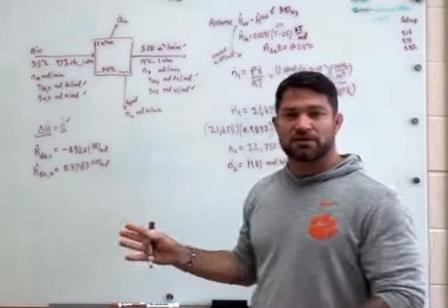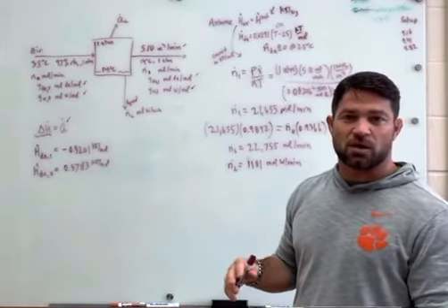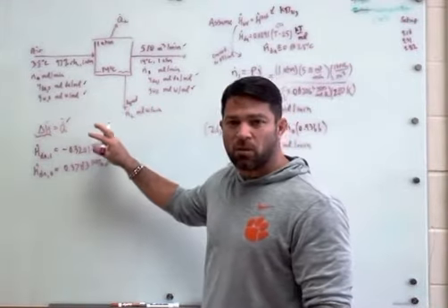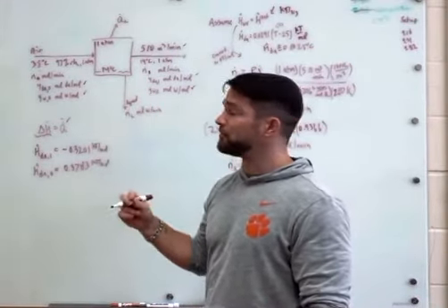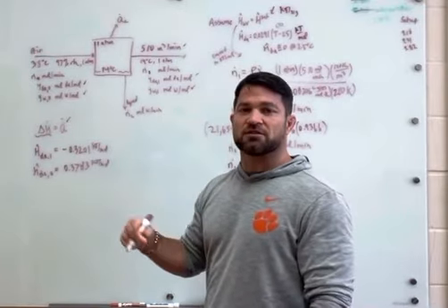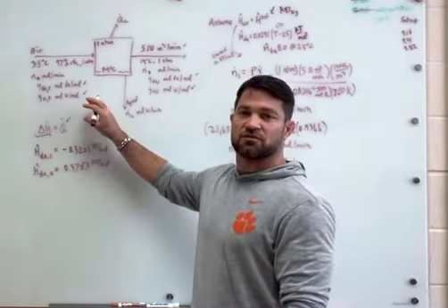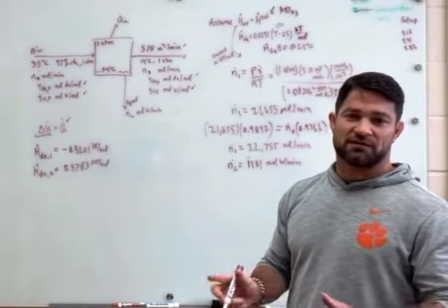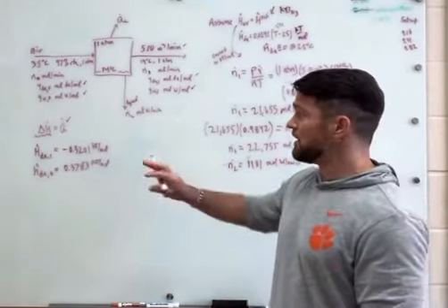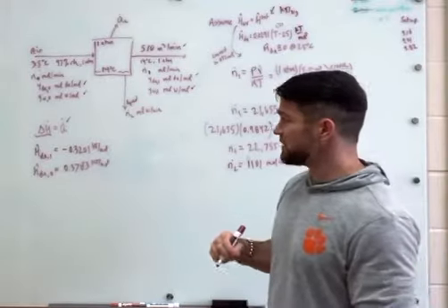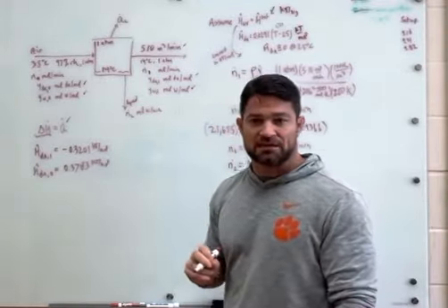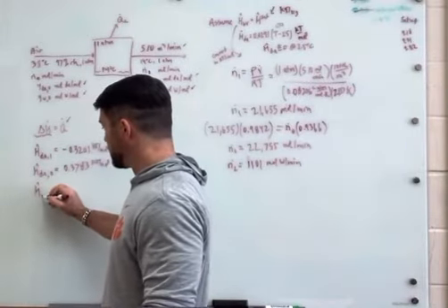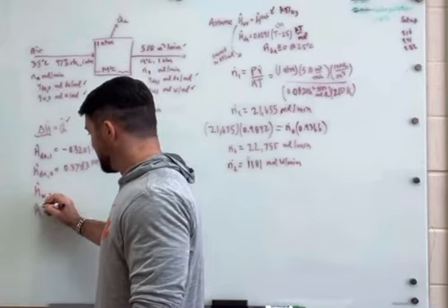And it's okay that we have a different reference state for each one, because we're effectively calculating the change in enthalpy of the water. It's all versus the same reference state, and then also the changes in enthalpy of the dry air. For reactive processes, though, you have to have everything at the same reference state. So if there's no reaction, you can use different reference states for different species, and that is all fine. Okay, so what now? We need the enthalpy of the water coming out, we need the enthalpy of the water